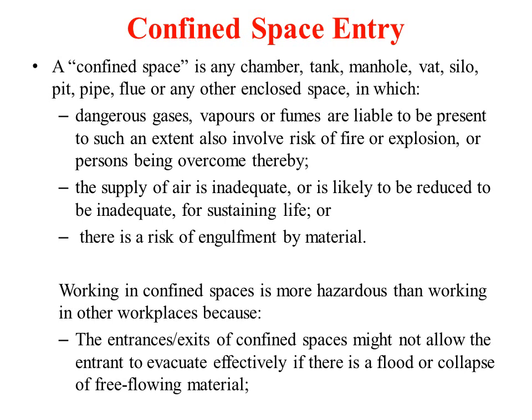There's a risk of engulfment by the material. That means we may get engulfed by whatever materials there are in the confined space. There are chances of dangerous gases, vapors, or fumes in such an enclosed space, and the person can be overcome by them, so that he may not come out of it.